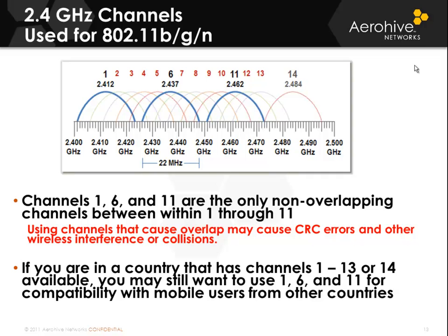If you were using OFDM, that separation would move up to 5 MHz because each channel would only be 20 MHz wide. The next channel in which this phenomenon occurs is channel 11. So you can see quickly why channels 1, 6, and 11 are more often used than other channels. It allows us to co-locate 3 devices without reusing channels at all, breaking up the contention domains properly.